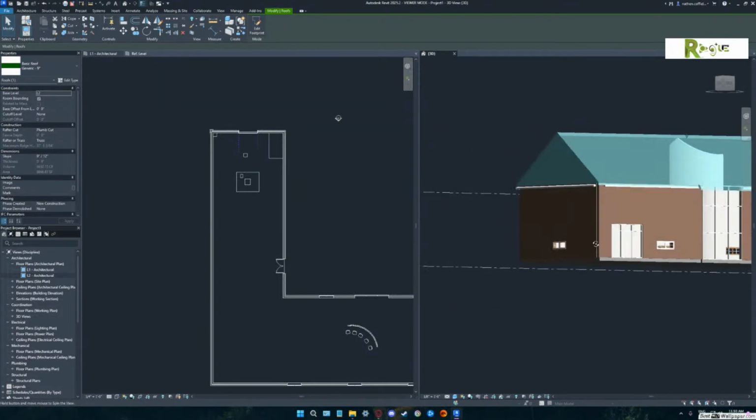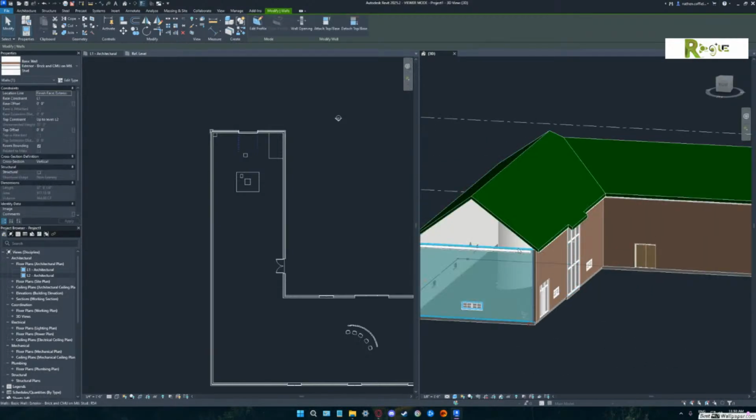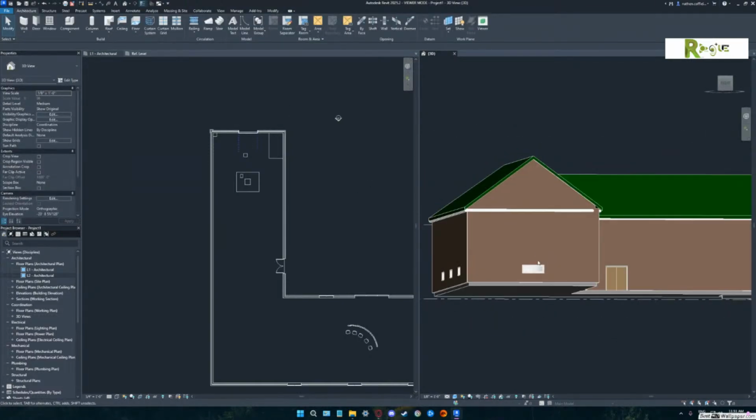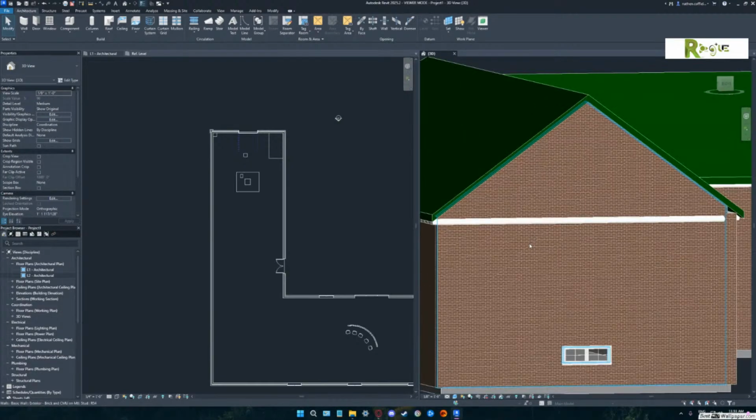Now the only thing you would have to do is click on that wall. And you see where it says edit profile, wall openings, attach top and base, detach up in the menus. Yep, say attach top base. And then click your roof, and then click in clear space. Oh, okay, so I got you. So it makes it the wall instead of the roof. Exactly. Now you don't have the hip, and you're going to see both of those conditions a lot.